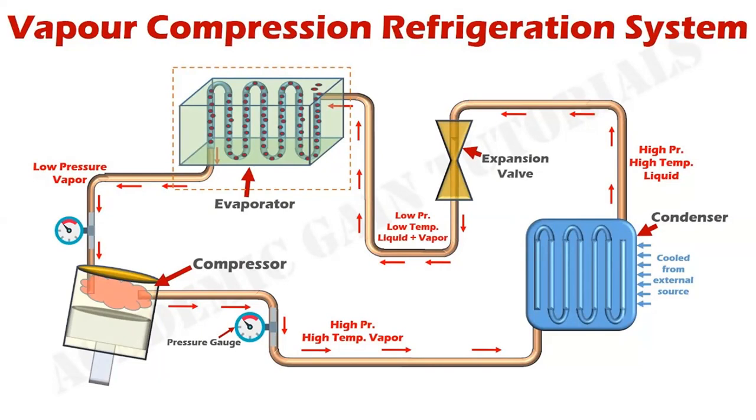This is achieved by using a substance called a refrigerant, which absorbs heat and hence boils or evaporates at a low pressure to form a gas. This gas is then compressed to a high pressure in compressors, such that it transfers the heat it has gained to ambient air or water and turns back into a liquid, that is, gets condensed into a liquid. In this way, heat is absorbed or removed from a low temperature source and transferred to a high temperature source.